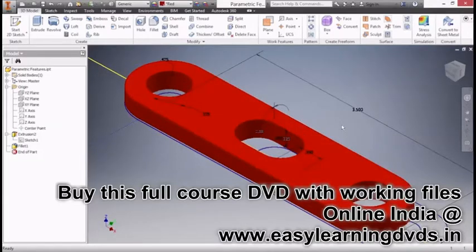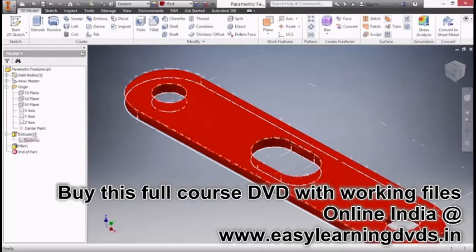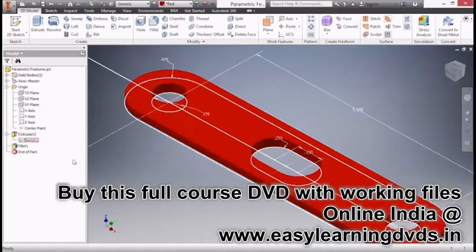Nothing happened here. Nothing really updated with the feature model. You can see the underlying sketch updated, but the overall geometry has not. Whenever you use the Show Dimensions method of design, you have to force the update to actually take place. So if I go up here to my Quick Access toolbar, there is a lightning bolt icon. If I click on it, it will force the update of the model so I can see everything change. If you were to use the sketch editing or the feature editing directly, that doesn't happen. You can basically update it automatically when you finish the command.